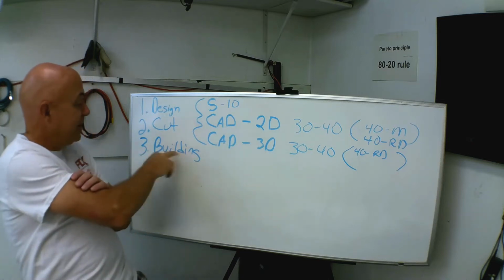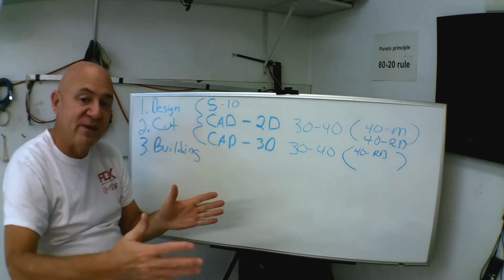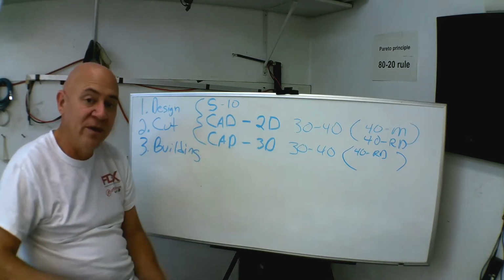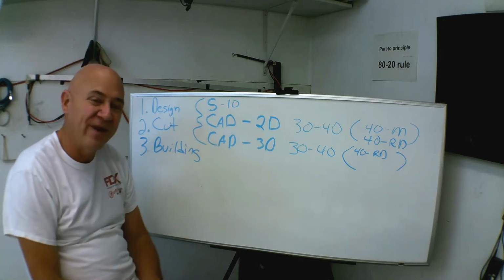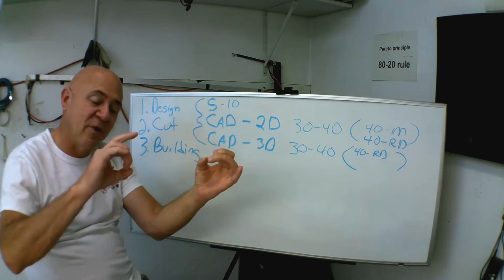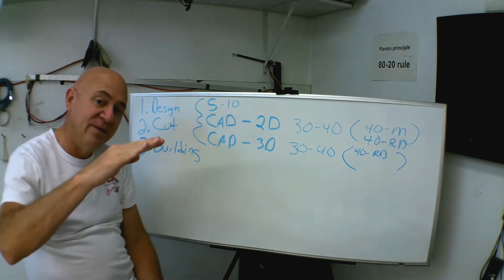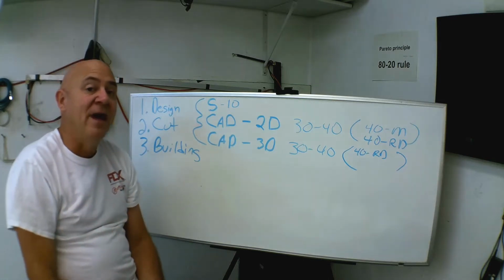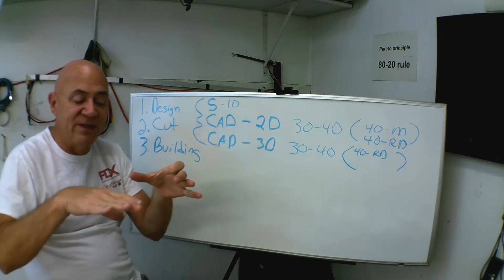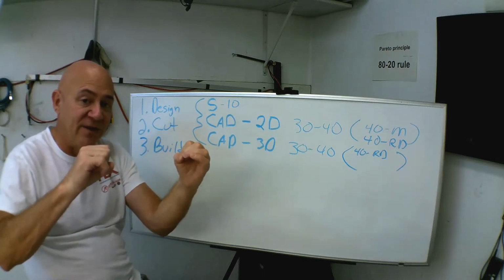So now let's say you're building, and you have your wing center section. You put on the right wing, all the inserts lined up. You put on your left wing, 3 degrees off. And you're like, what the hell did I do wrong there? There's 2 spars. The back spar, because the jig was off 3/16 of an inch, has tilted the wing. So now you've got to go back, because where your wing plugs in, you're going to have little pins that the wing will plug into to lock in the inserts. Those 2 spars don't allow it to lock in.